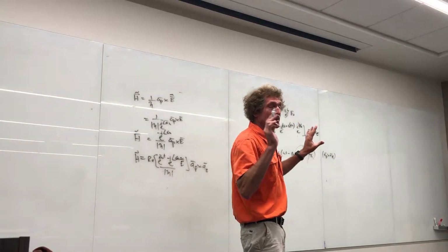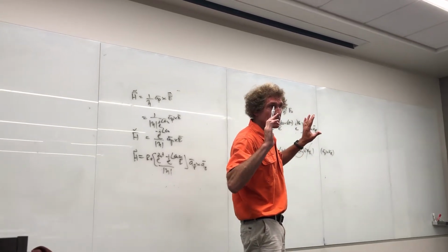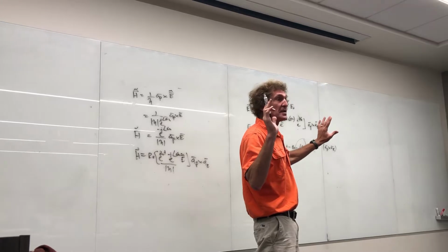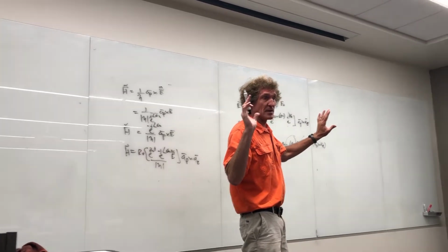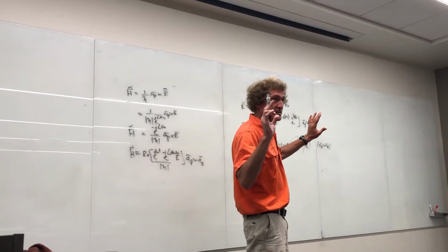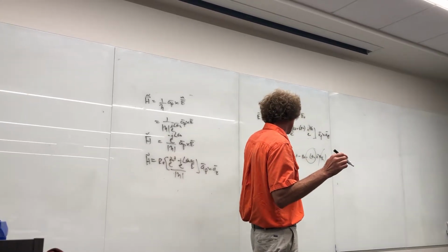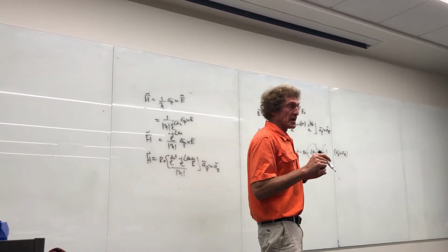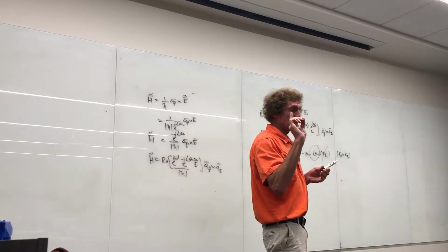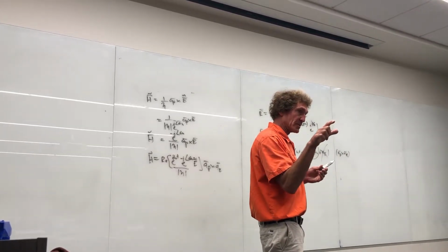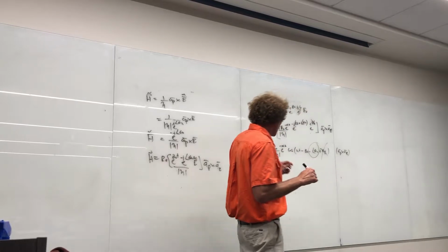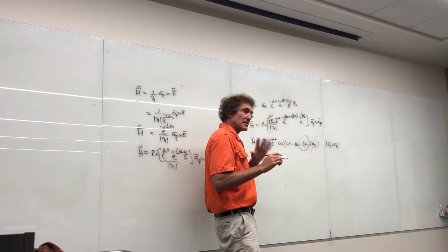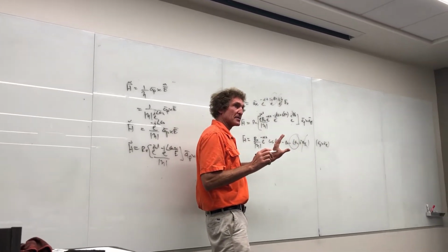When you're dealing with things that are propagating in a media that's lossy, if there's no loss, then E and H are in phase. Remember that. They have identical equations except for the magnitude in front and the orientation. And you can always get the orientation because E cross H is the direction of propagation. Remember that. But this is like an inductor. The media we're in here is like an inductor.